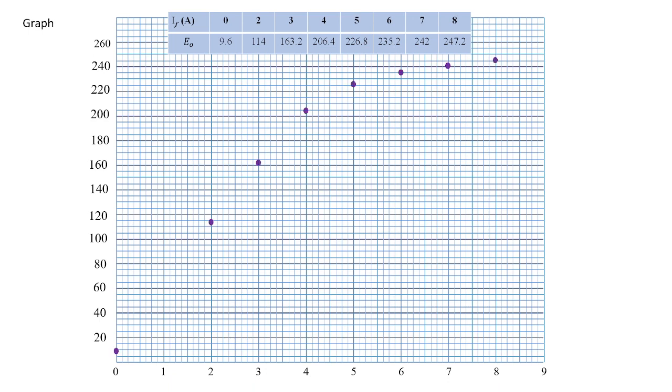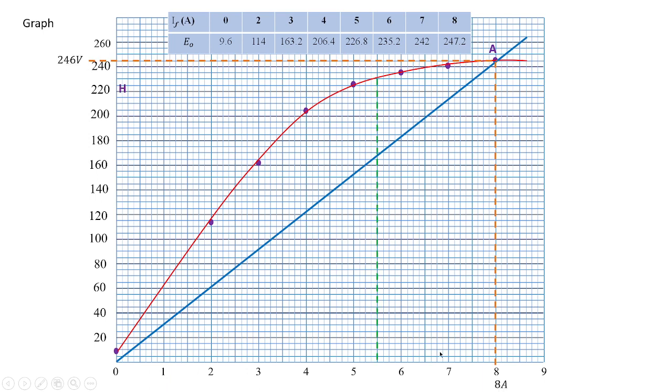So the OCC is drawn like this, and 30 ohms is given. Approximately for 30 ohms, here you can see 20, above that you have 30, beneath this 40, the center line. So for 30 ohms, this is the shunt field resistance line, and the machine will be excited at approximately 246 volts, that is at 8 amperes the value is 246 volts. So this is the saturation voltage.